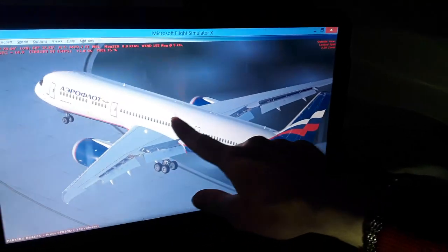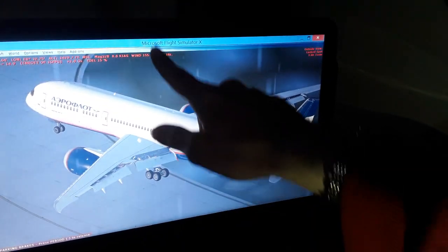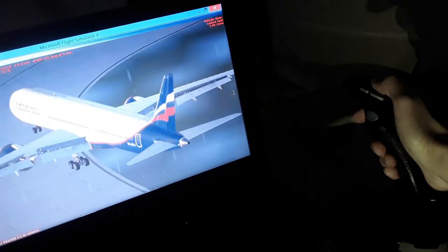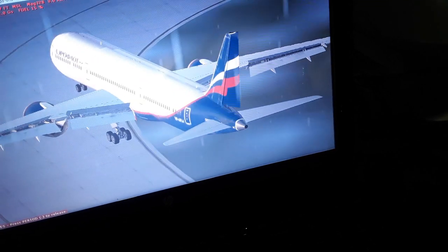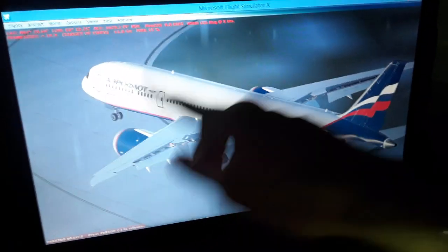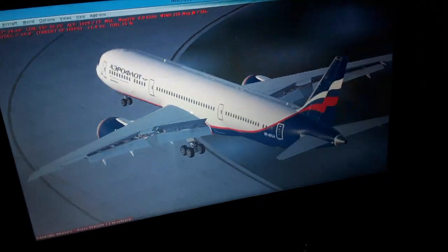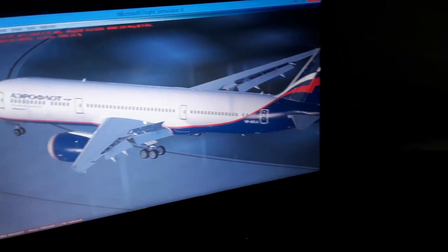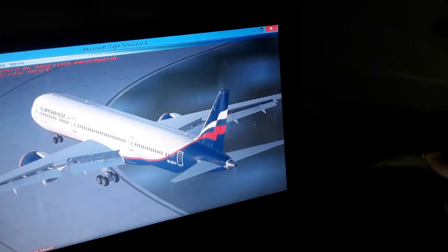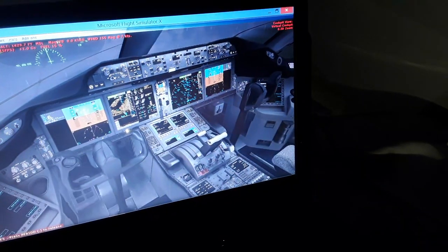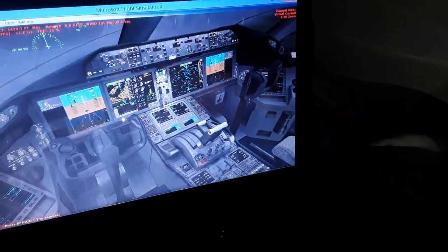So the main aerodynamic chord position is where the yawing axis is, the center of gravity over here. So we can yaw the aircraft through the center of gravity using the rudder, left and right turns in the air. Also the nose wheel steering over here, the forward nose wheel steering on the ground, is used simultaneously with the rudder control by moving the rudder pedals automatically from the computers. You don't need to do anything for that.